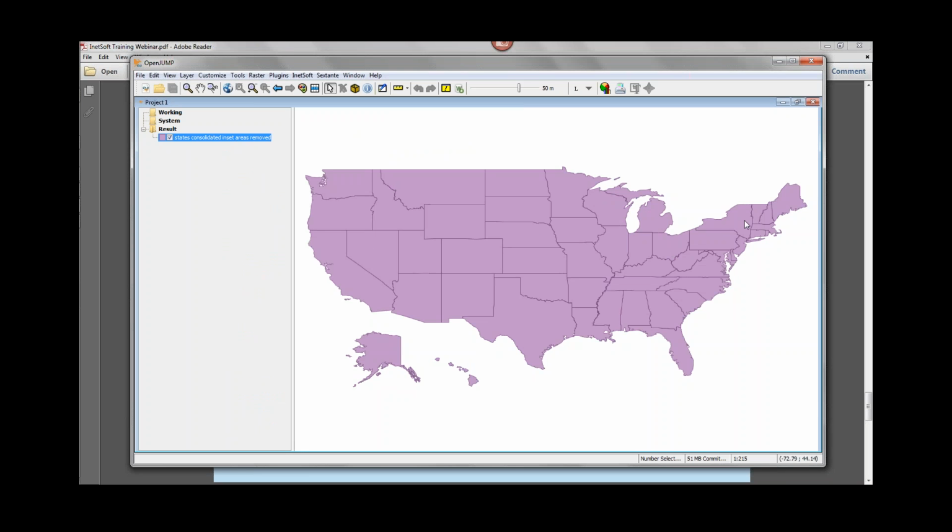And you can see that fundamentally there have been no real distortions of the map, so that value seemed to preserve the map okay. And of course, what you might want to do in that case is see if you can push the limit a little bit more, maybe remove a few more polygons, maybe try a larger threshold value, and maybe you can still have a usable map with even fewer polygons, and that would be better for memory. But I'll leave it like this for now. The next step of optimization is reducing precision.